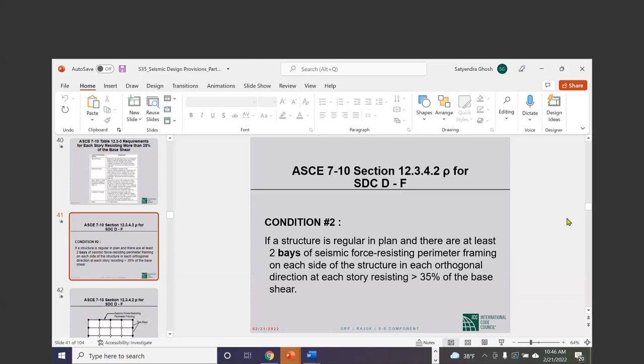So you have to design for the shear, you have to design for the bending, and the basics still apply. If you have high compression, you will have to confine. Other than that, there is no particular detailing requirement. Okay.